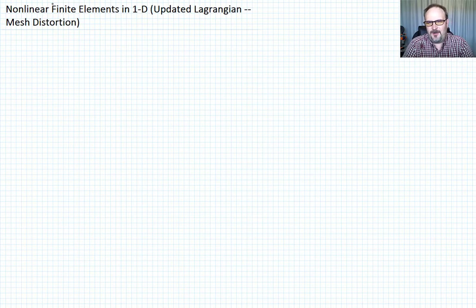In this lecture today, I want to talk about the importance of mesh distortion and how it affects the Jacobian and how it affects the actual results of what we compute in a finite element analysis. So let's begin by considering some three-node quadratic element.